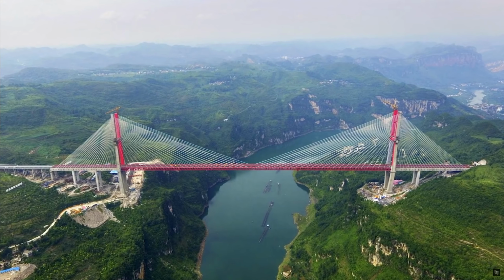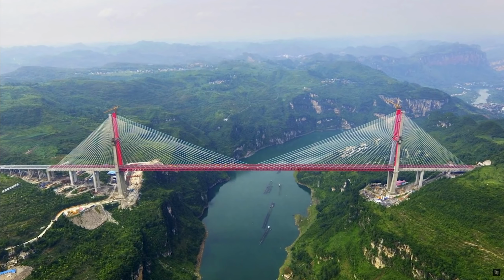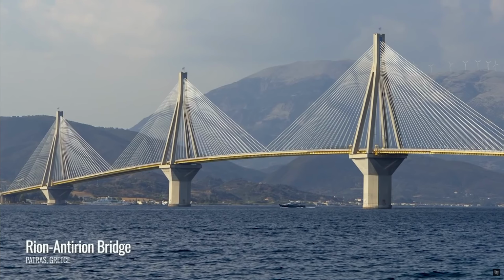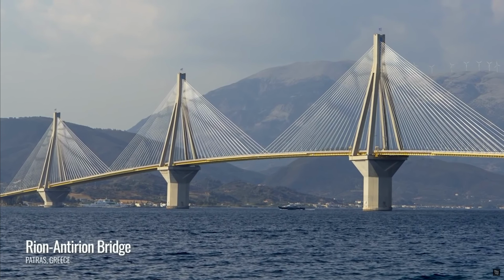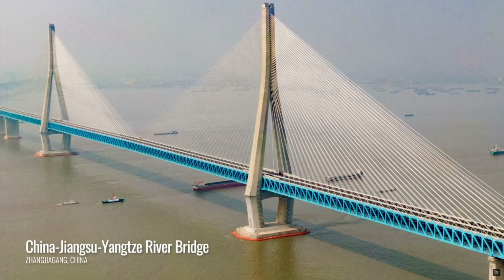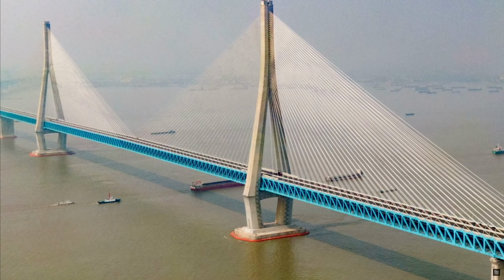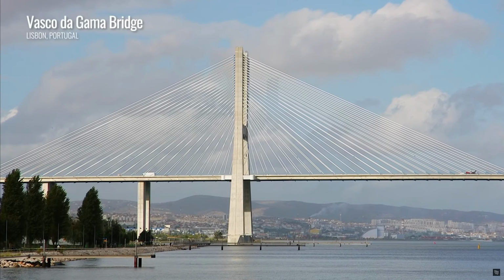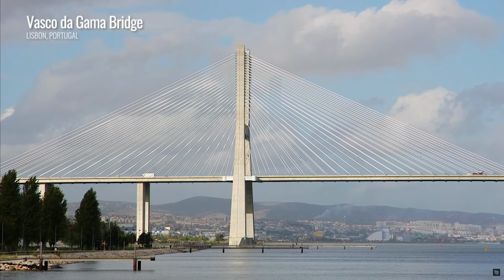What's another type of bridge? Another similar cousin, I like to think of, to the suspension bridge is a cable stayed bridge. In this case, they're similar in that there are towers, primary supports that then connect to the ground. But instead of having two main draping cables, the cables are attached directly from those towers, from those piers, to the deck. Each side of the tower sort of acts as a counterweight to the other side.